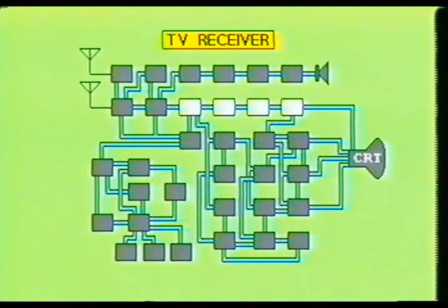Here you see the heart of the video image circuitry. The signal produced at the output of the final amplifier stage in this string is known as the Y or luminance signal. The Y signal is responsible for the video image which is shown on the TV screen. The Y signal controls the brightness levels within the picture tube, thereby producing an image ranging from black to white.